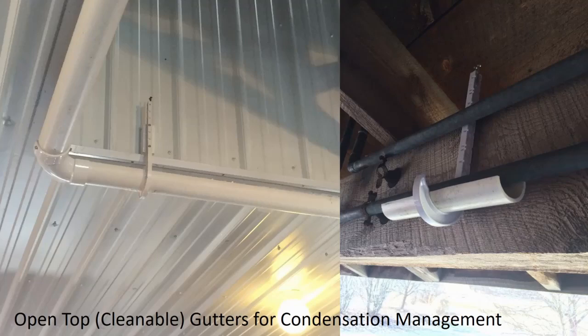Condensate and dripping is another challenge we run into with respect to contamination sources, whether it's in coolers on the left-hand side, or in the case on the right-hand side, cold water lines that are used in hot, humid areas. What we're showing here is some clever folks who have used PVC piping as a gutter. The gutter collects the dripping condensate that would otherwise drop down onto produce handling areas. With adequate pitch and an outlet hose barb that runs to a hose, for example, and out of the building, it is directed away from where it might lead to contamination.